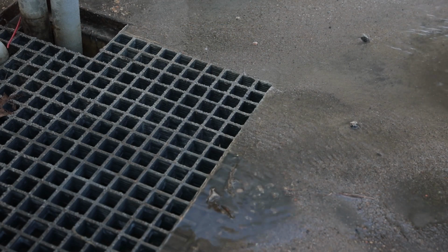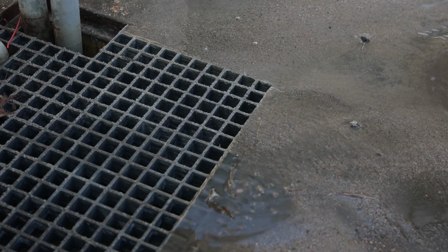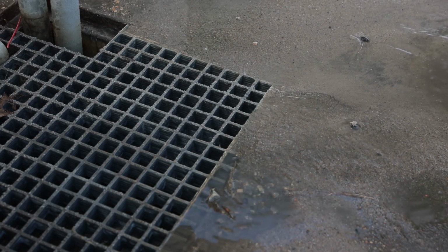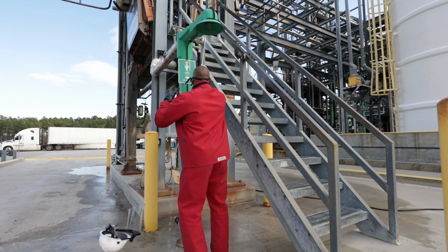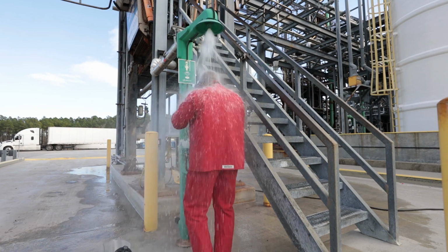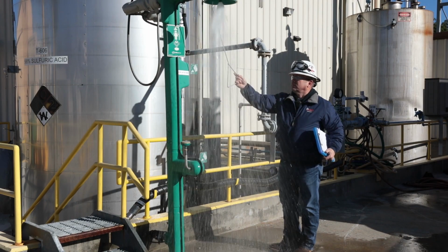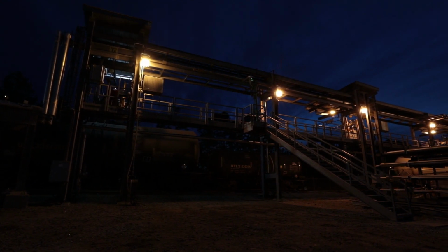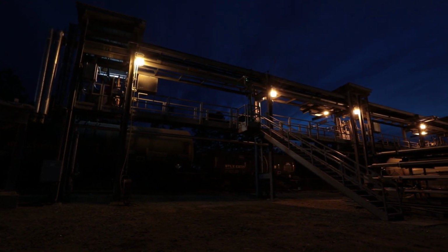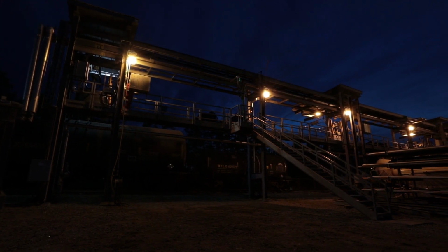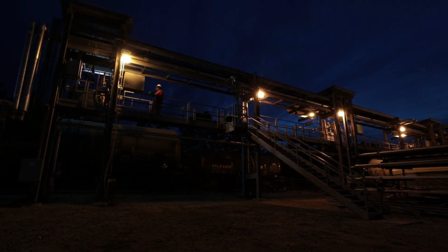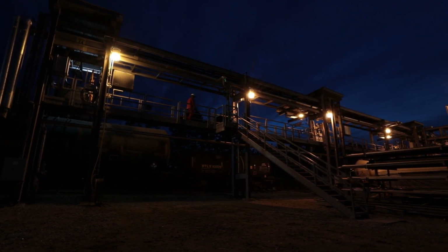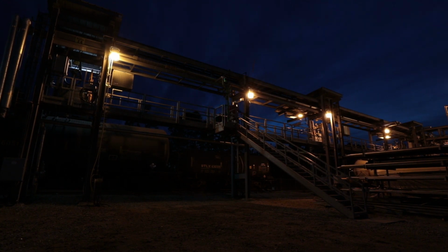The unloading area for both tank cars and tank trucks should be constructed so that any spillage that occurs will be properly contained for recovery or disposal. Emergency showers and eye wash facilities should be located close to the unloading operation and should be checked for proper operation prior to unloading. Special attention must be given to lighting in the area since adequate lighting is needed for safe nighttime operation. Even if night operations are not contemplated, effective lighting should be installed as an aid in dealing with possible nighttime emergencies. Emergency lighting should be available in case of a power failure.